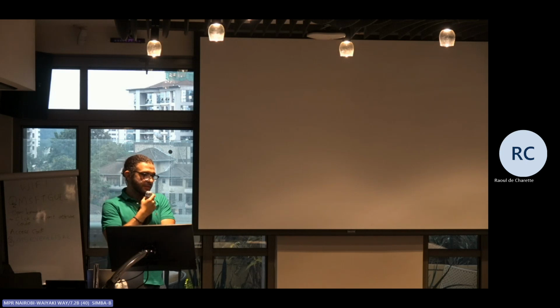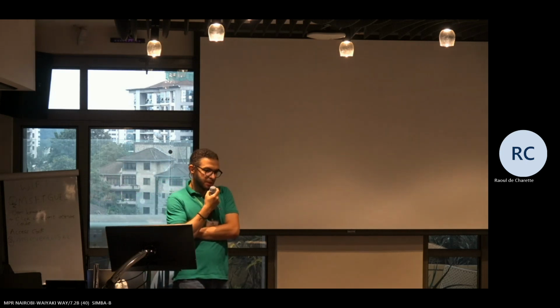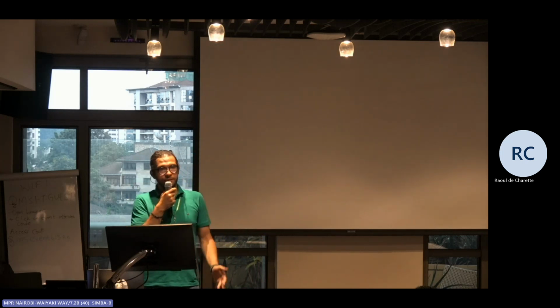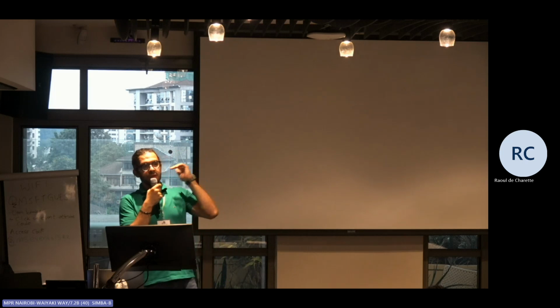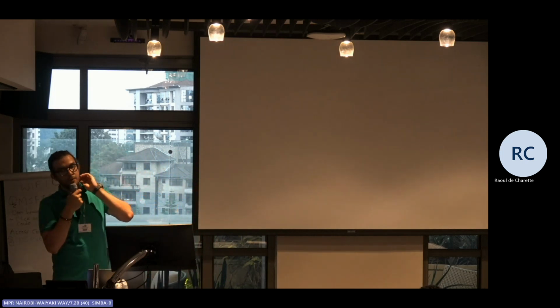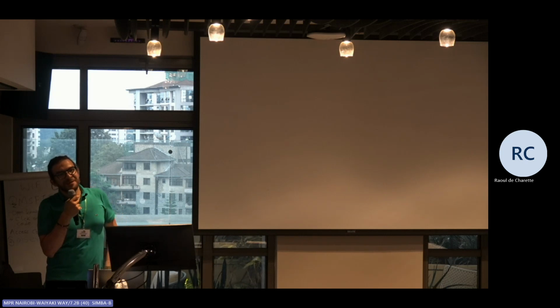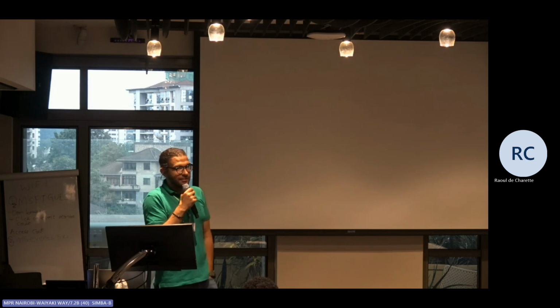So basically, taking white balance for example, usually after every single step we do clipping. That's a traditional step in the camera ISP. So every so often we lose some information, lower or higher. Of course, that information is useful, but how we can keep it, I don't have any thoughts, to be honest, unless we keep a residual or some novel idea beyond what we are doing.